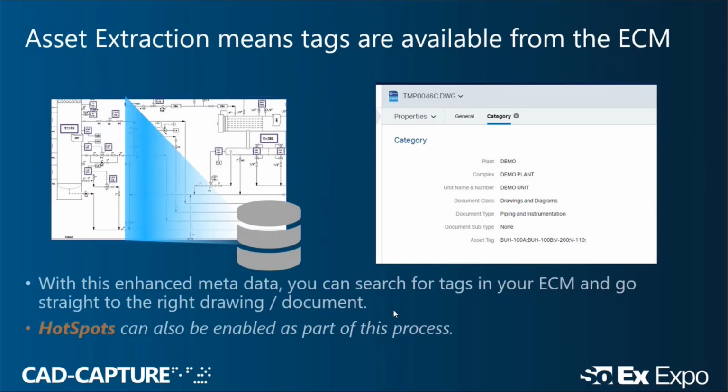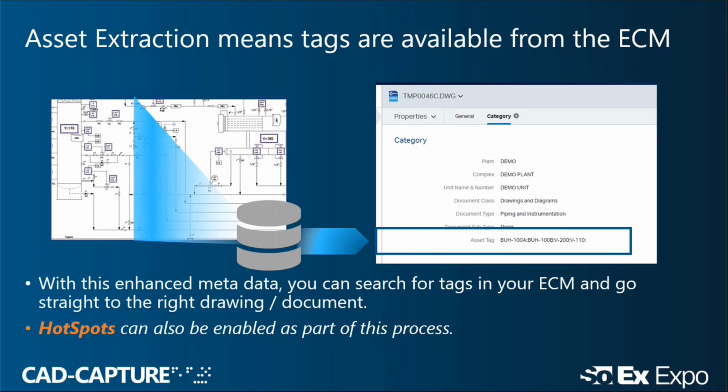Okay, so firstly, once the asset information is extracted, and again, we categorize it and validate it, it's important that it is shown to deliver the value it can, which means that not only do we validate it against what it should be, but we also give the ability to correct it. So sometimes people will use the wrong naming convention, or if it's a PDF, the OCR results will be inaccurate. So as part of our capture and extraction process, we can build in a rule that will allow us, at the metadata level, to save the name of the tag as it should be, rather than as it necessarily is if it's inaccurate. And that means you can standardize and correlate information in other systems very readily.